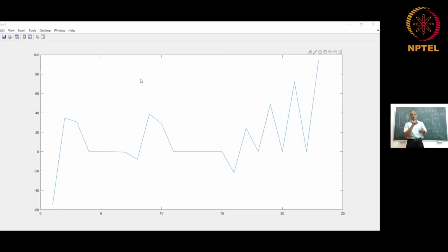Now theta equal to A into 1 minus e to the power of minus bt. Since I've taken the average as an assumed value of A, theta by A is known. 1 minus e to the power of minus bt, I will linearize, and then I will use simple least square regression. I'll get an approximate starting initial value for B. That will be the time constant.